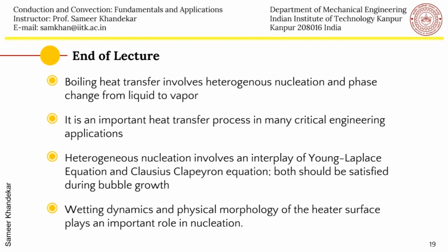So you will see later on that rough surfaces are actually good because many nucleation sites get active. And if you have a very smooth surface, then the boiling superheat or the wall temperature which is required for boiling to take place is rather high, and therefore not good for heat transfer applications.